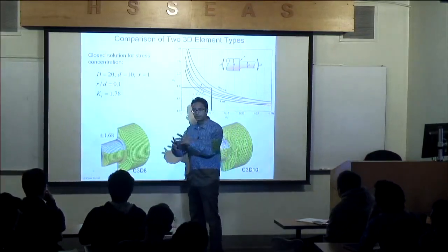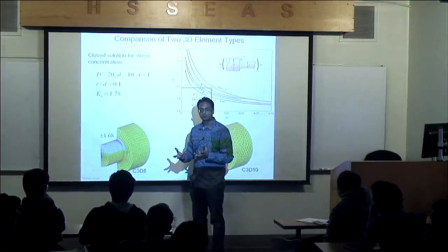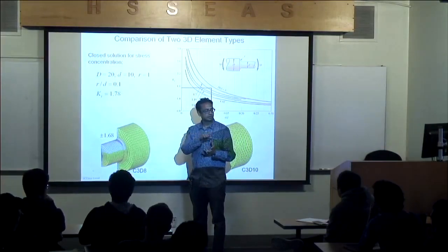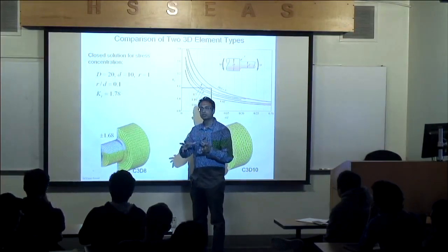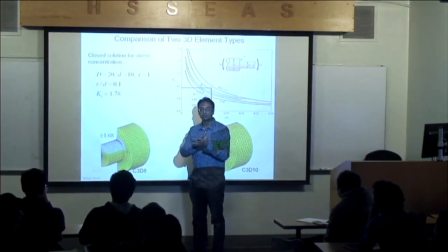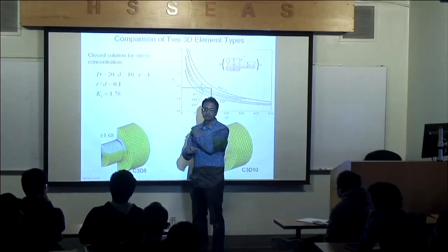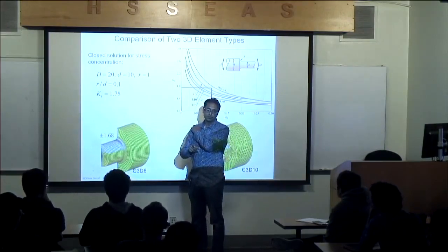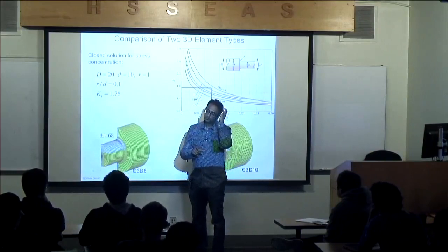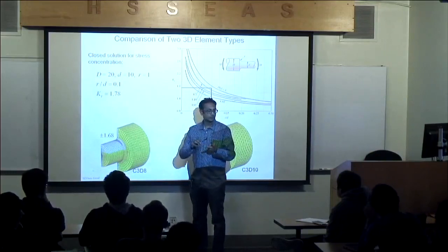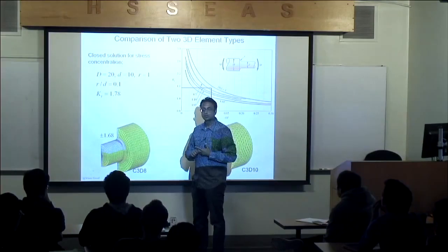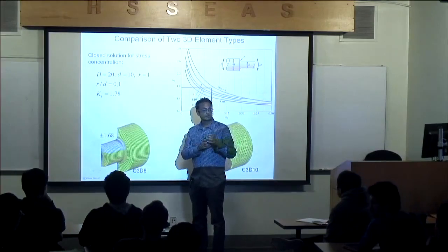I have a domain. You discretize the domain yourself because in Abaqus you'll mesh it, right? When you mesh it, you're actually telling Abaqus how to discretize that domain. What is Abaqus doing now? Well, Abaqus has the weak forms for each of these physics problems, heat transfer, solid mechanics, and Abaqus already has the shape functions, all of them.